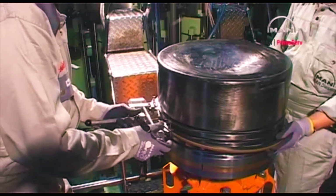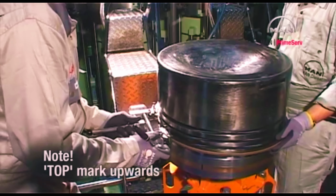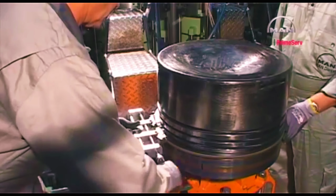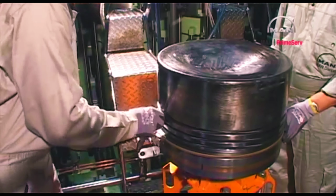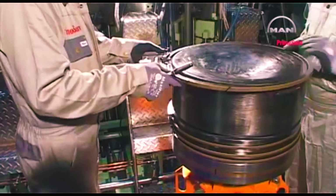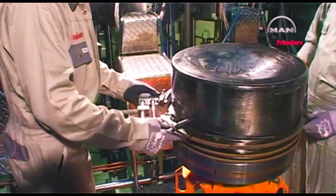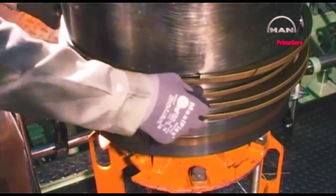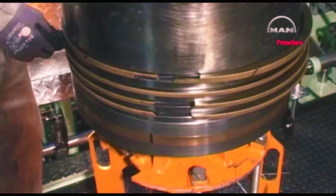Mount the piston rings with the top mark upwards and the ring gap staggered 180 degrees.